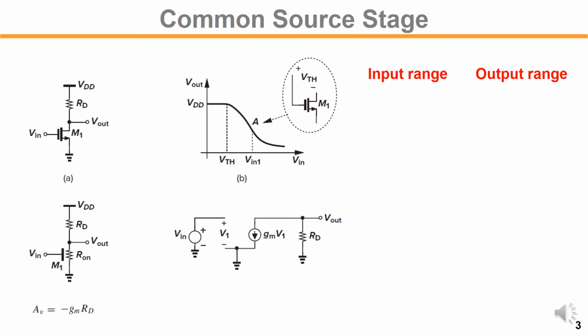In this example, we will see a common source amplifier design. To properly bias this, let's say the input is biased at VB, and on top of that bias we apply a small variation Vin. So around VB you apply some signal, and at the output you will see the amplified signal with some common mode.